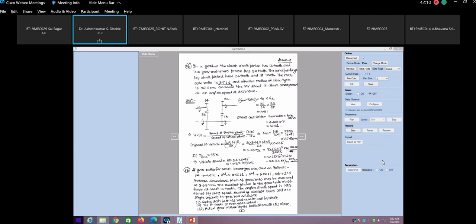So generally the gear ratios are most of the time in the range of, let us say, first gear ratio is 4.2, or hardly it ranges from 5 to 4. Okay, so usually this is the thing. Do you know the process of designing of the engine? See, an engine is never designed from a blank white paper. You have to have the research engine which is available. Then based on the criteria, you decide what should be the RPM, what should be the capacity, what should be the torque. Then you go on changing the parameters in the research engine and you try to get the parameters which you have targeted.